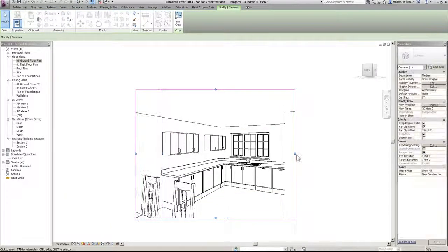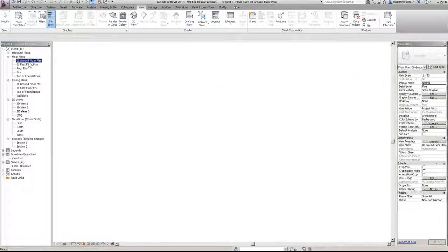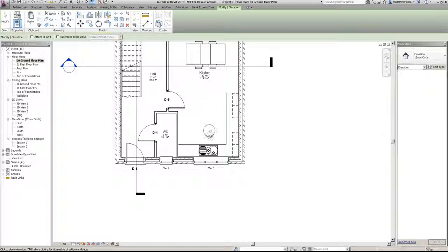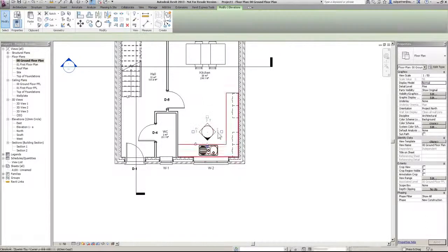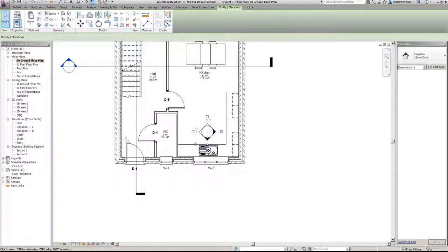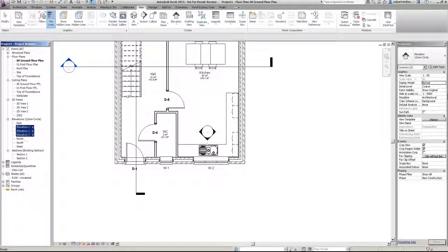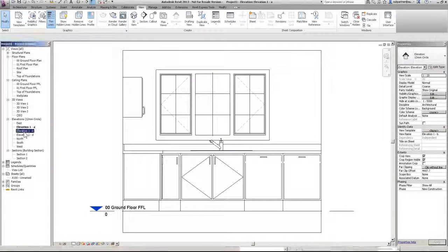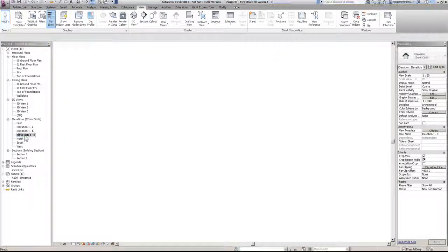It's not just there in 3D. What we can do, something I like to do, is throw a little room elevation in here. We've all done elevations, room elevations for tiling layouts, etc. in kitchens. Okay, I'm just going to click there, turn that elevation on as well. You can see it's making elevations in here, like so. I'm going to make these elevations 1 to 20s. Fantastic. When I go into them, as you can see, we've basically got my room elevations for my kitchen.